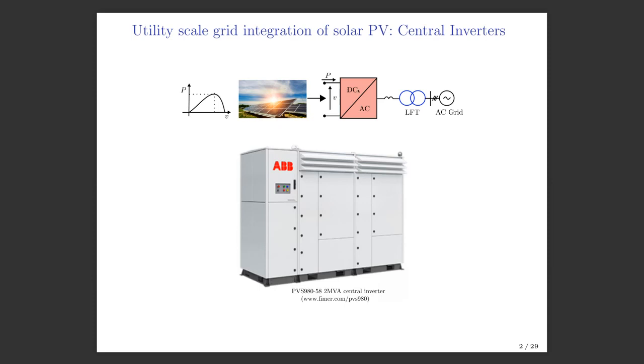So a three-phase DC to AC converter is employed to connect this solar field to the grid. This is also known as the two-level three-phase regular inverter. Now, this inverter is controlled in rectifier mode so that the voltage at this port can be adjusted to this particular voltage so that we can extract and push the maximum power into the grid.